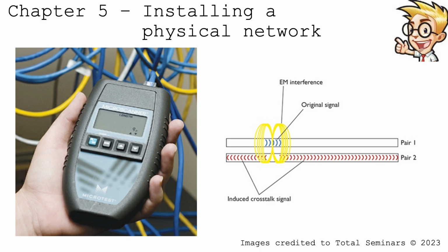Okay, time domain reflectometers. Some can tell you the length of a cable or where it's located and where it broke. So this takes a lot of guesswork out of it, but obviously these devices are much more expensive.